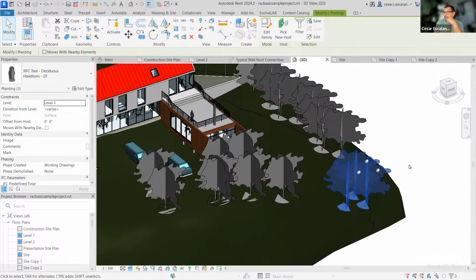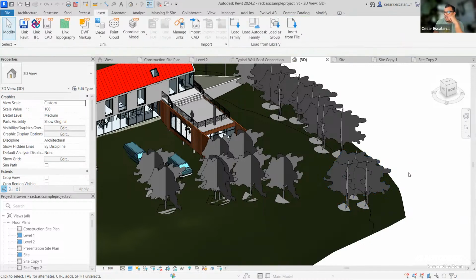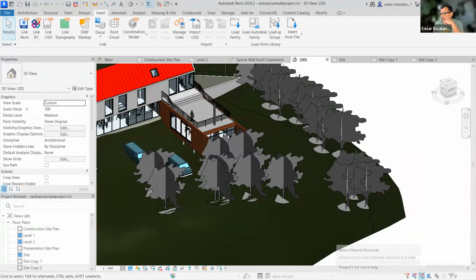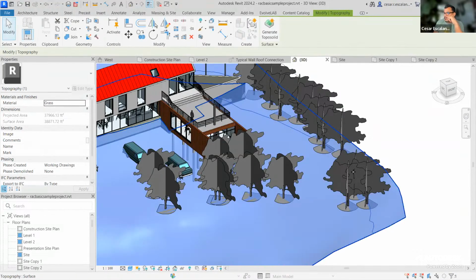And the purpose of a pin is to prevent mistakes from happening. So what are things that you don't want to move, like structural levels or columns or grids? Those are things that are usually set on a project early on, and they should not be changed. And so when you pin something and you disable the user ability to select it, the pin object is not selectable. Look, I'm clicking in the middle of this pin object.